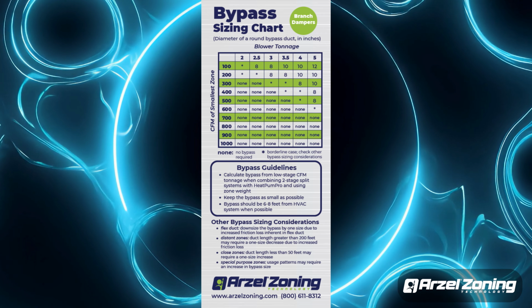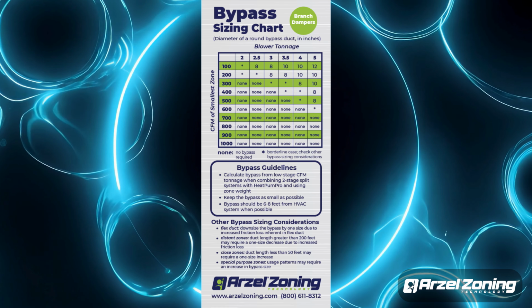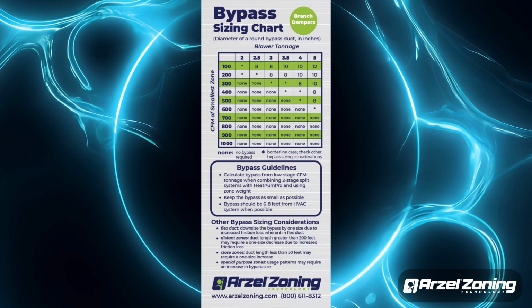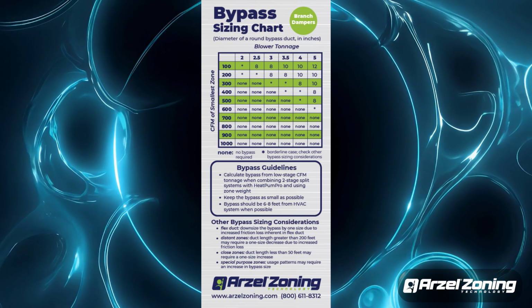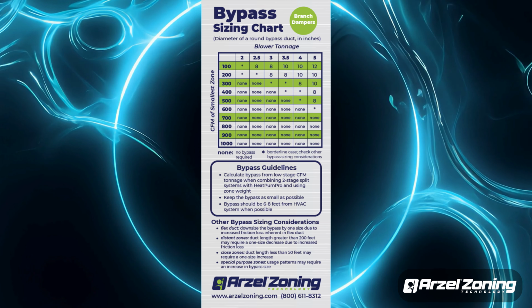Now the Modupass comes in 3 sizes, 8, 10, 12. I call it small, medium, and large. 8 is our most common. 10 we sell a few of, 12 we sell very, very little of. For me, I kind of use it also as a barometer. If you do a bypass calculation and you need a 12, that might be more of an indication you should go back to the drawing board and see if you can make that zone a little bit bigger.